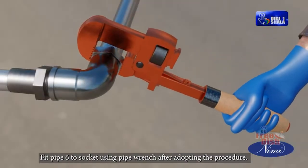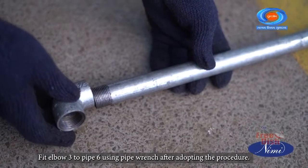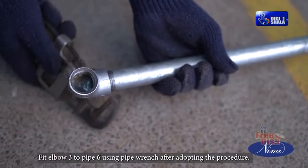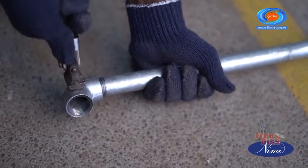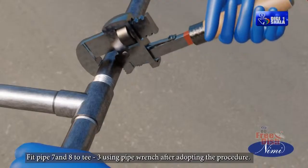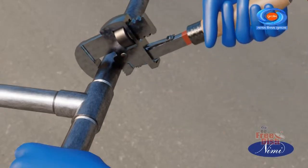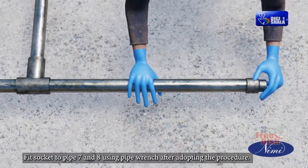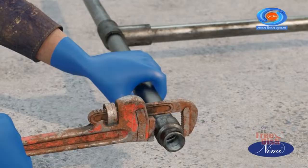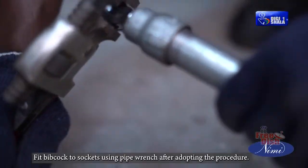Fit pipe 6 to socket using a pipe wrench after adopting the procedure. Fit elbow 3 to pipe 6 using a pipe wrench after adopting the procedure. Fit pipe 7 and 8 to T3 using a pipe wrench after adopting the procedure. Fit socket to pipe 7 and 8 using a pipe wrench after adopting the procedure. Fit bibcock to sockets using a pipe wrench after adopting the procedure.